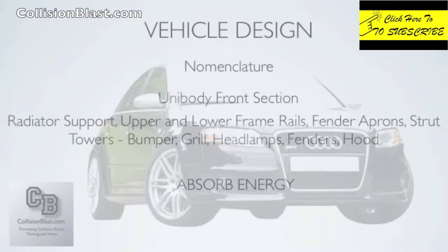Well, they do have frame rails, but what unibody means is uni means one, so it just means everything, including the frame rails, are welded together to make one piece, rather than the body over frame, where the body bolts to the frame. So on a unibody, you get the radiator support, which consists of several pieces, and you get the upper tie bar and the lower support, where the headlights bolt in. All that's part of your radiator support.